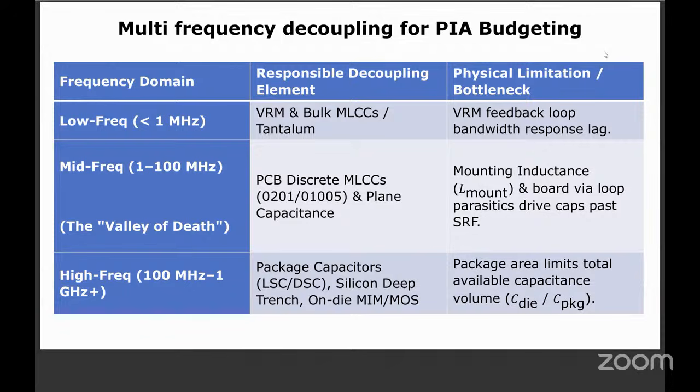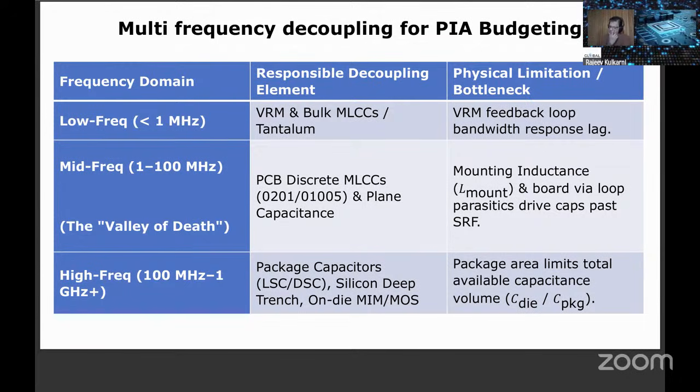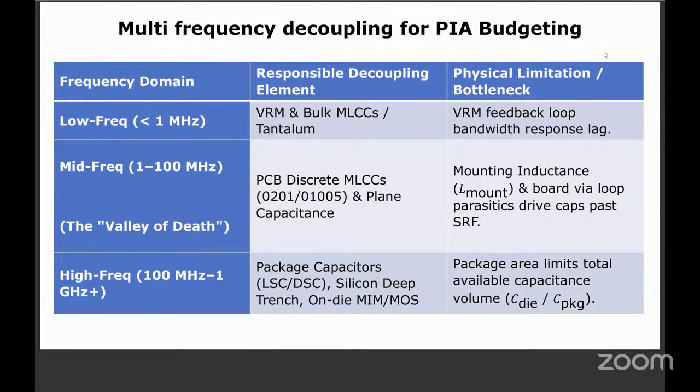Long time back, there was an application note which said a tantalum capacitor should be distributed within the width of a coffee cup. A coffee cup is hardly 2 or 2.5 inches. It should be within that. But now the package itself is larger than this, so the old thumb rules will no longer apply. I hope I cover this in the next sessions.